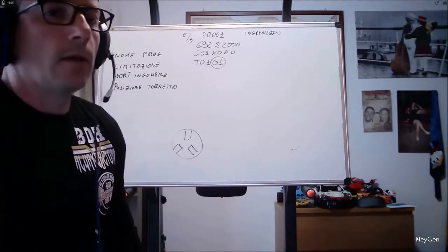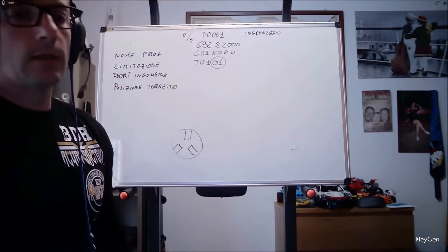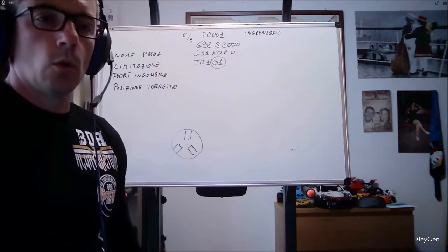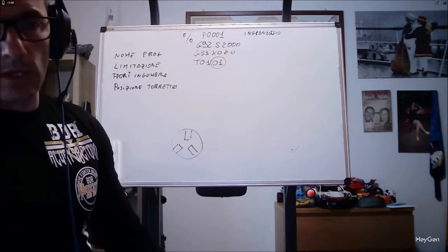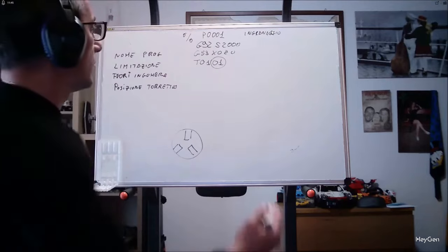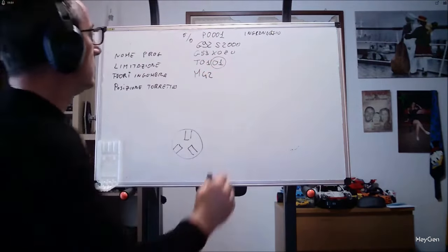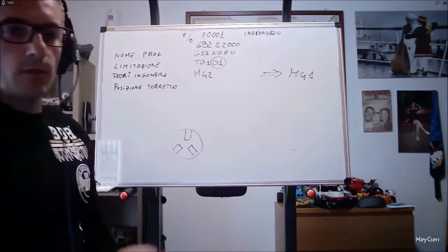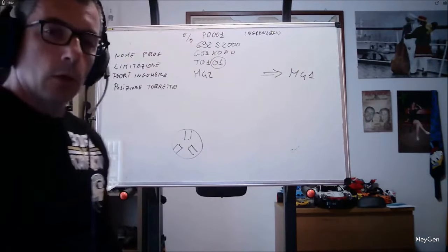The range, that is the gear, neither more nor less, the gears of the car. The car has 6 gears, the lathe has 1, so none for small lathes, 2, or 3, M41, M42, normally, so 2 ranges. If we do not specify it, the lathe will start in the last range set, M42, high range, or M41, low range. What is the difference between the two? The difference is established by the manufacturer and communicated to you.